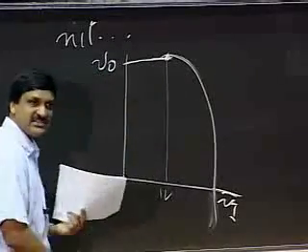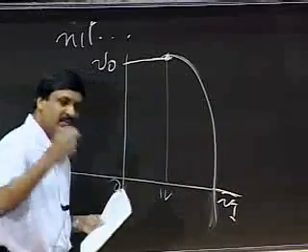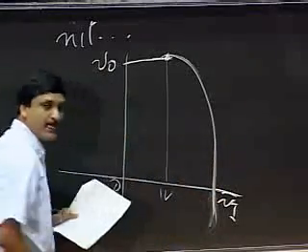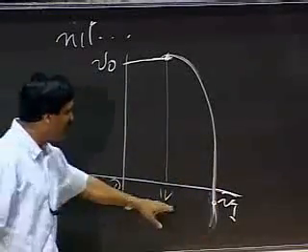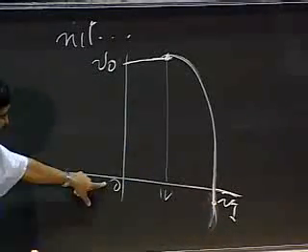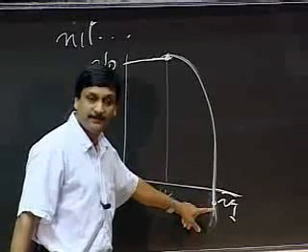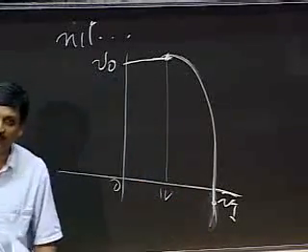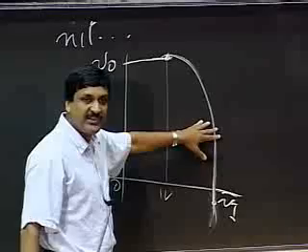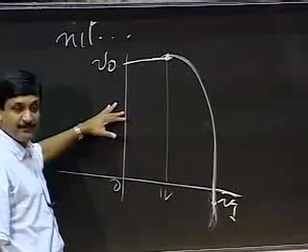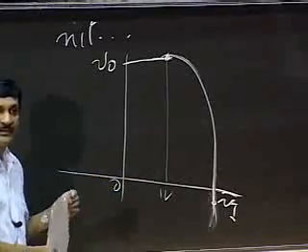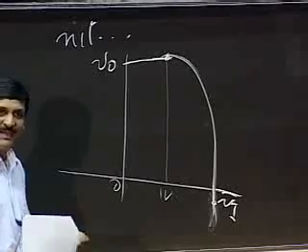If it's a passive device, you're going to say something doesn't make sense here. Mathematically, it says it should look like this. But what's special about a point down here? It says that the output has gone negative. This is 0 here. The output has gone negative, and my current source is still supplying a current. Up here, the voltage across the device is positive, V0 is positive, and it's supplying a current, so it's consuming power. It's burning power like a resistor. Like all bad little resistors do, they burn power.